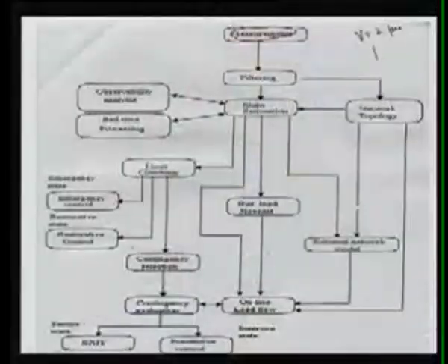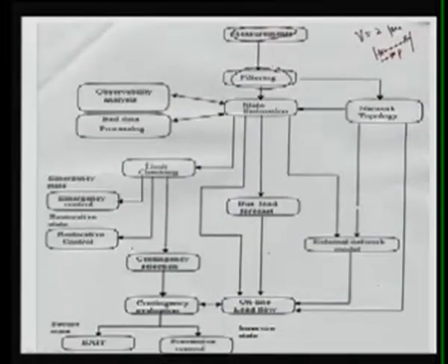Suppose for a transmission line, the circuit breaker status at both ends says that the circuit breaker is open, and also it says that there is some power flow in this line, which is not possible. So both pieces of information are contradictory to each other. Based on this information, we can filter out some of the absurd measurement data, and that is called filtering of the measured data.